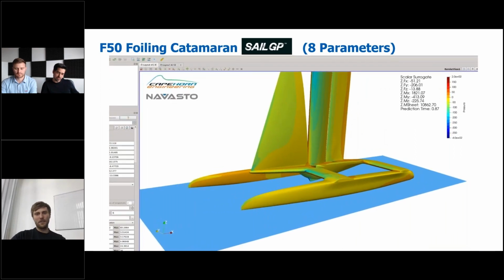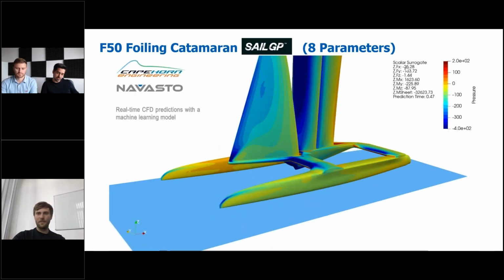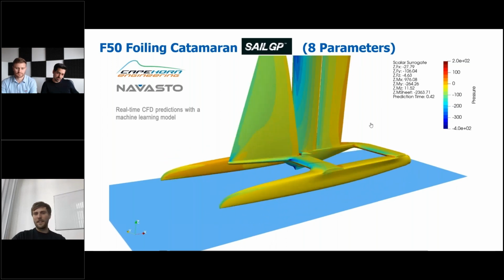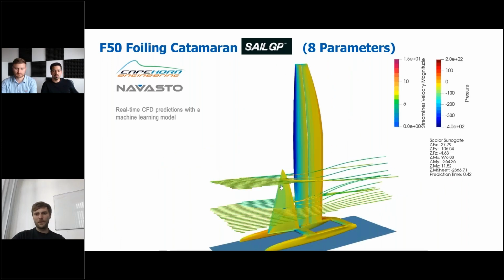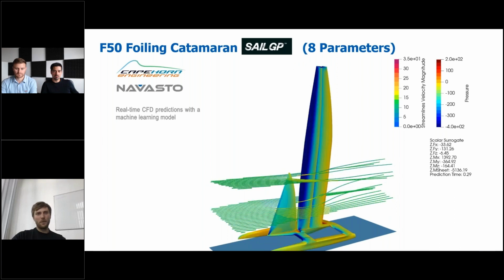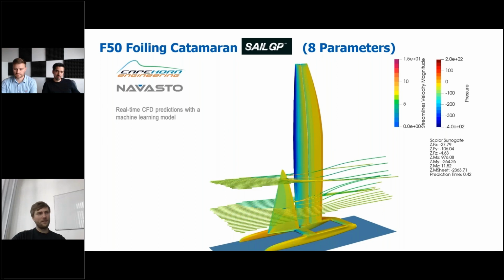You get the instant feedback on the surface pressure and also on the scalar values, like pointed out on the upper right corner. And this is another use case. It's really testing thousands of geometries, also involving the volumetric flow field like this, and really finding optimal configurations. So the real benefit is that you have basically unlimited iterations to really reach a goal and to be competitive without running thousands and 10,000s of simulations. You just need around about 100 simulations to build a model, and then, as I said, run thousands of predictions.